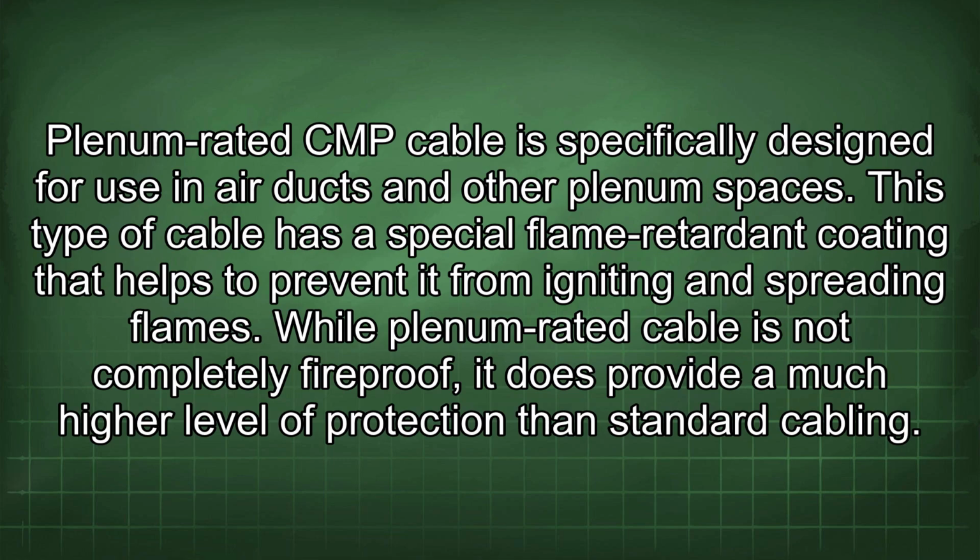The enumerated CMP cable is specifically designed for use in air ducts and other plenum spaces. This type of cable has a special flame retardant coating that helps to prevent it from igniting and spreading flames. While plenum rated cable is not completely fireproof, it does provide a much higher level of protection than standard cabling.